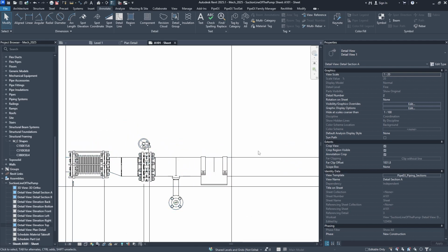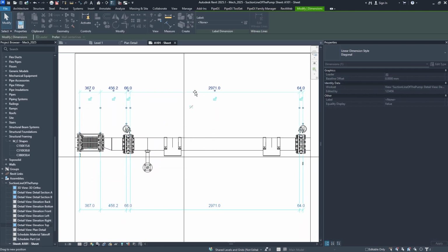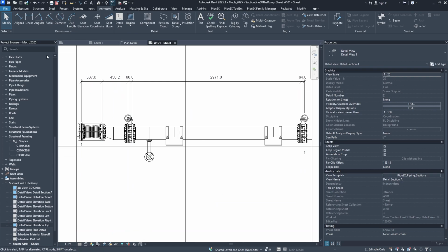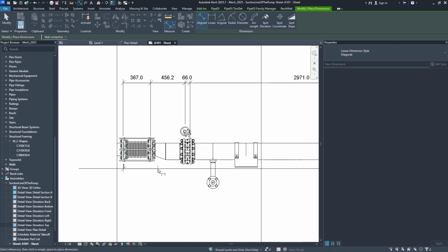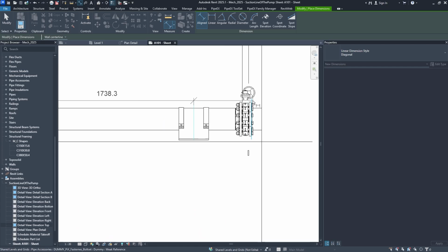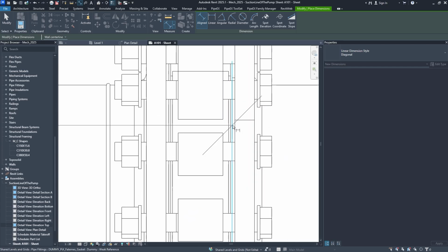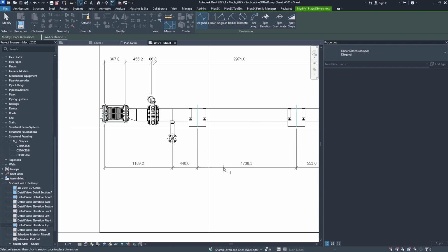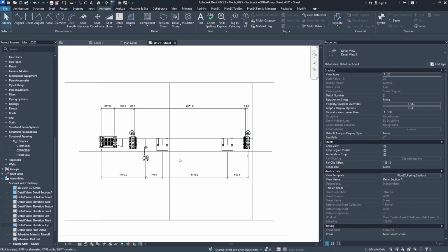Then of course you can add all the annotations here. If you would like to, you can move these dimensions to the top. Then you can indicate or give some generic dimensions, for example, location of the tab point, location of the support, and the total dimension towards the equipment. As you can see here, we don't have a floor mentioned, but you can add it.